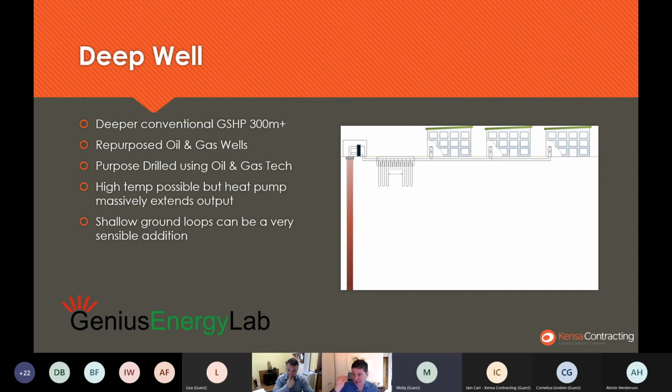That could potentially be used for electrical generation, but in the UK, because we've got a relatively cool crust underneath us, you soon strip that well of its useful energy. So what we're looking at is using that heat directly to heat buildings, and then stripping more heat out of it to fuel heat pumps at very, very high efficiencies. Quite cool stuff, all at the cutting edge. The other thing I've come to realise in doing this study in Aberdeen is that coupling these systems with shallower closed loop can be really interesting, and the economics of that are fascinating. I haven't got all the answers on that yet, but we are working on it.